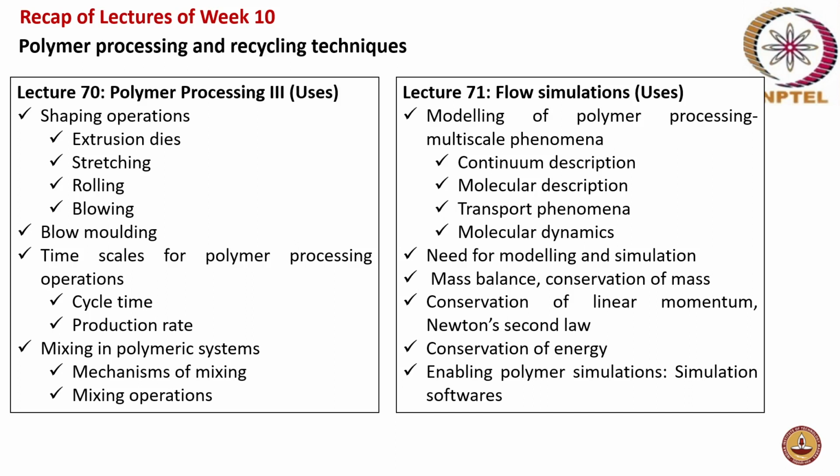It involves mass balance, momentum balance, energy balance, species balance, and then evolution of volume fraction, orientation. These equations are all solved based on the continuum description. There is also molecular dynamics and coarse-grained dynamics, which is based on the momentum balance, which is nothing but the second law of motion solved for the molecular dynamics.